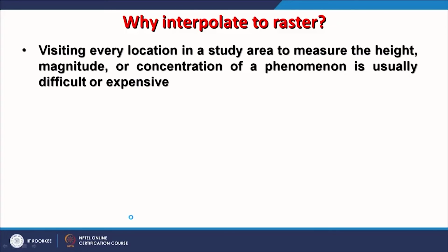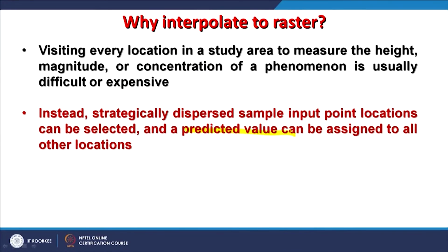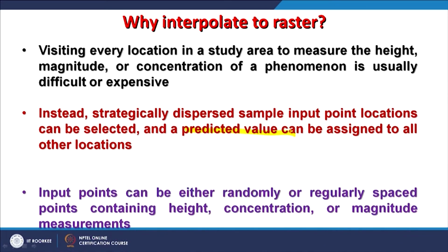As you know, visiting every location on the surface of the earth and collecting height information is impossible, because there are terrains which are very difficult for humans, and it is not possible to generate a surface for the entire globe. So some techniques have to be employed. One technique is, wherever it is possible, collect the heights, employ interpolation techniques and generate a surface, or predict values for each cell. That is what we are doing in interpolation.